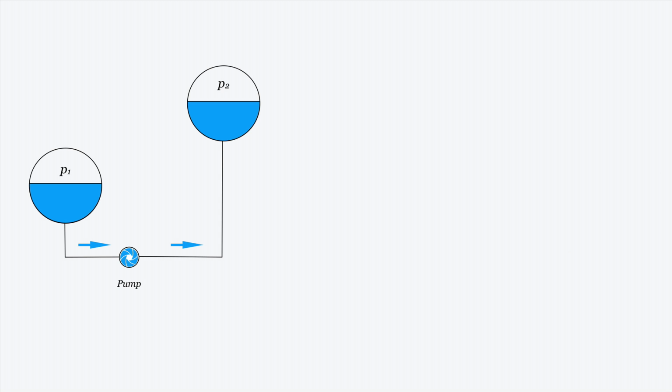So we will have a low pressure P1 on the deaerator, and we will have a very, very high pressure P2 on the boiler drum. The same as before, let's establish the datum plane here, and the sections will be located also over the liquid surface in order to eliminate the velocity head term.